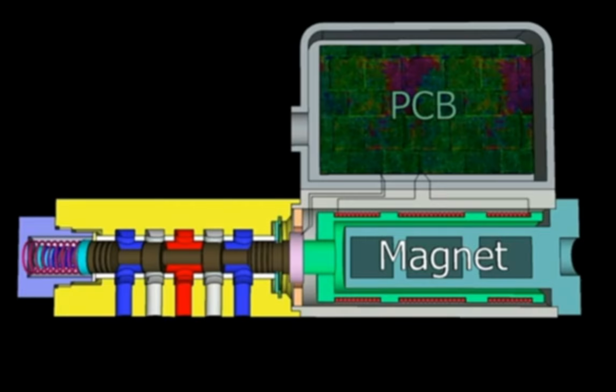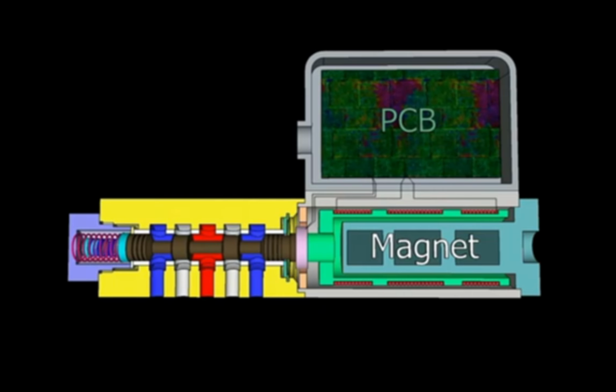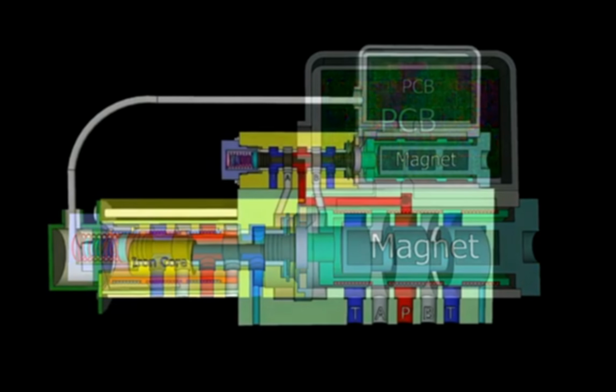The end of the pilot valve has a self-centering spring which fails safe. Whenever the power is switched off, this will become centered, and this pilot valve is fitted on the main spool valve, which actually allows the high pressure oil to the fuel oil pressure booster.